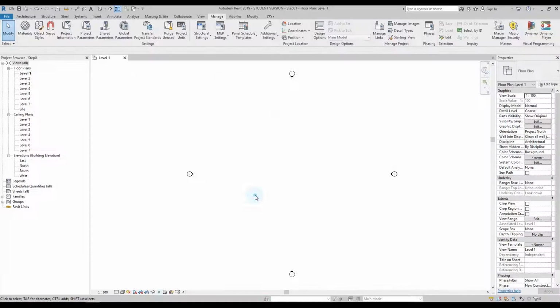In this window you will notice that we have area, volume, angle, slope, currency and mass density. If you want, you can have a muck around with these and change these. Generally I like to make sure that the decimal point is rounded to 0, and that's usually the case on all of these. Like this one here is 2 decimal places. I generally don't like that and usually have 0. But again, as this is a training session, it shouldn't really matter. So once you've done that, press OK.